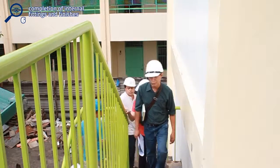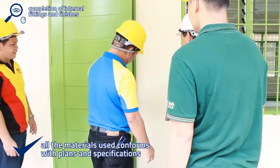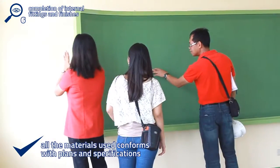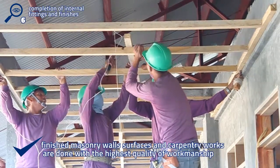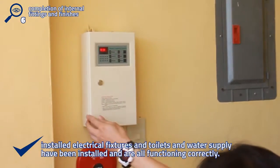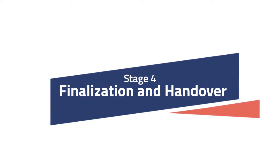The engineer should carry out key inspection point 6. The engineer must check that all the materials used conform with plans and specifications. This is particularly important in respect of door fixtures, the blackboard, and the security grills. That the finished masonry wall surfaces and carpentry works are done with the highest quality of workmanship. That the installed electrical fixtures, toilets, and water supply have been installed as per plan and are all functioning correctly.